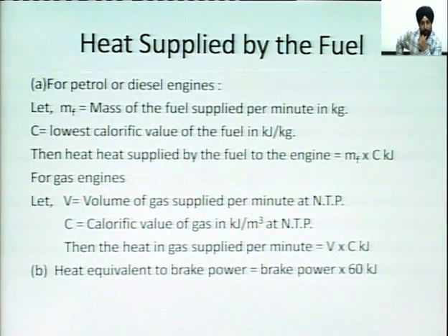In this case, because we have taken the case of a petrol engine, but it can also be written for a diesel engine, suppose mf is the mass of fuel which is burned in a given time period, suppose in 1 minute, suppose in 30 minutes. C is the calorific value of the fuel. It is that amount of energy which we receive by burning 1 kg of fuel.